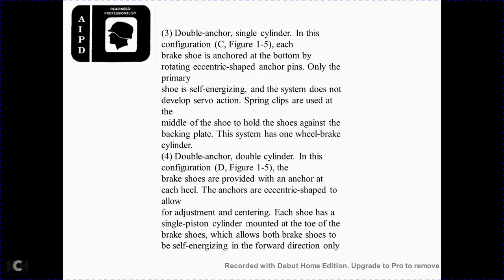Each heel with the anchor is eccentric shaped, allowing adjustment for centering, and each shoe has a single piston cylinder mounted at the toe of the shoe, which allows the brake shoes to self-energize in the forward direction only.